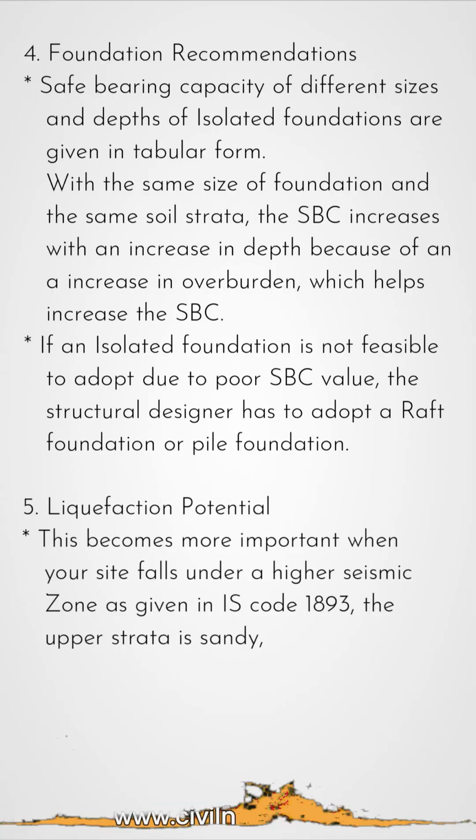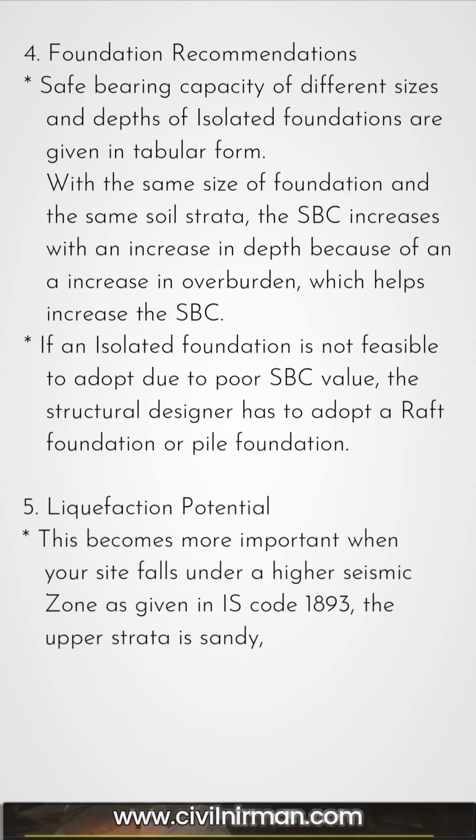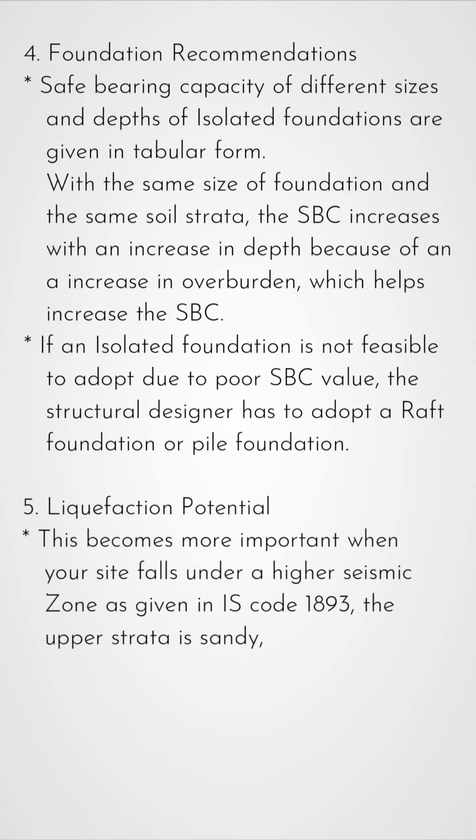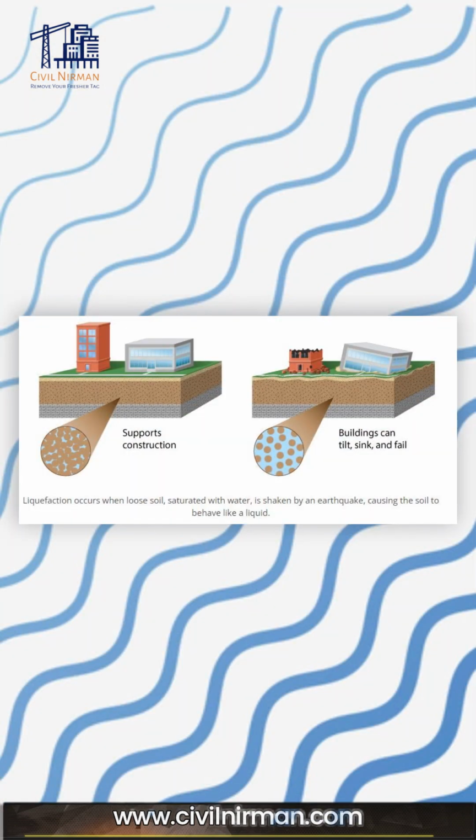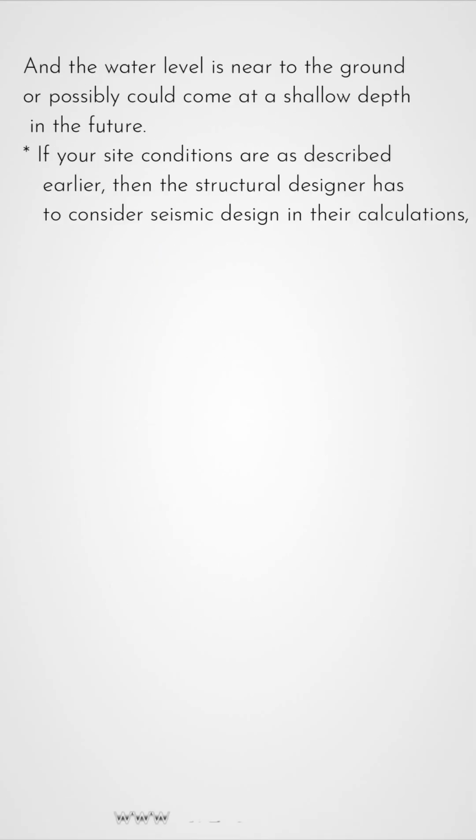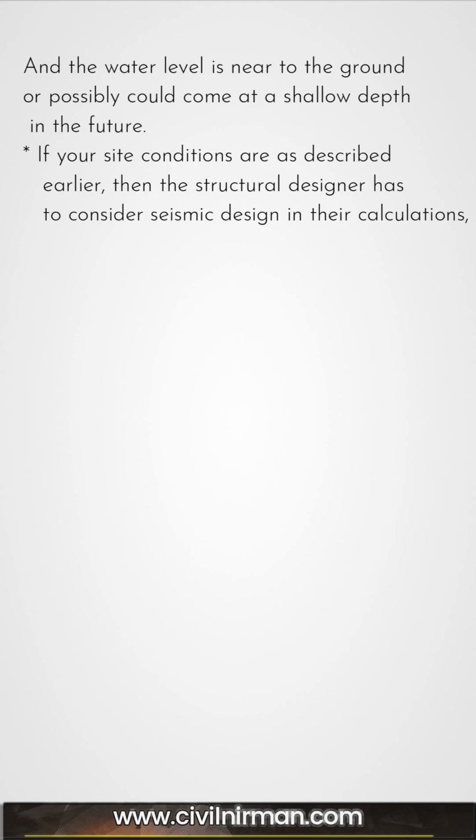Fifth important parameter, the liquefaction potential. This becomes more important when your site falls under a higher seismic zone as given in IS code 1893, the upper strata is sandy and the water level is near to the ground or possibly could come at a shallow depth in the future.